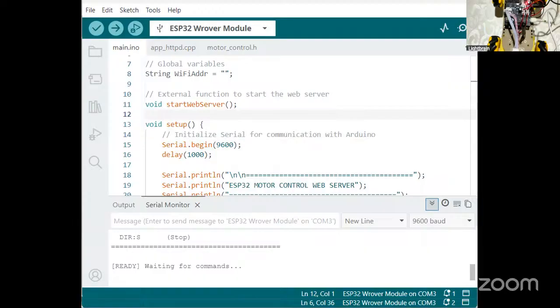And the ESP32 for this project number 3 is just there to connect to the Wi-Fi, to start the web server, and to wait for the button to be pressed and send the command to Arduino. That's all that you are doing on this part. If it's too much, just let us know in the chat box and we'll give more explanation. We are just trying to see how fast we can do so that everyone can get something.